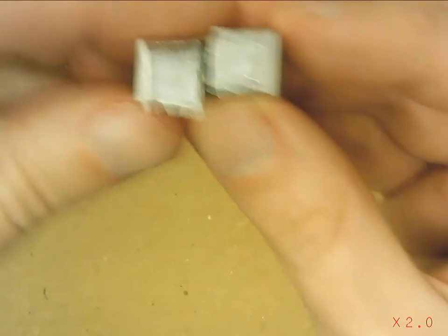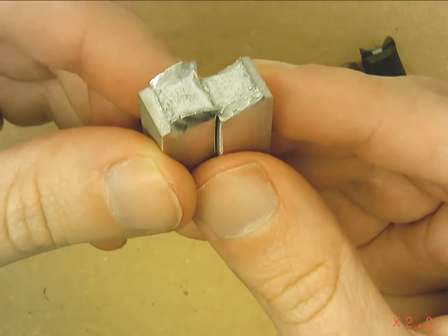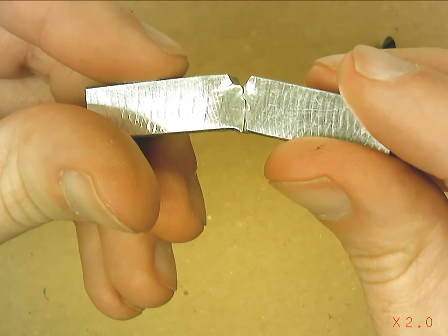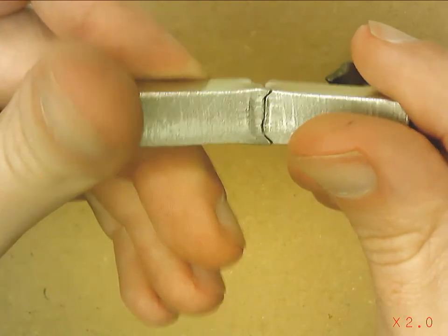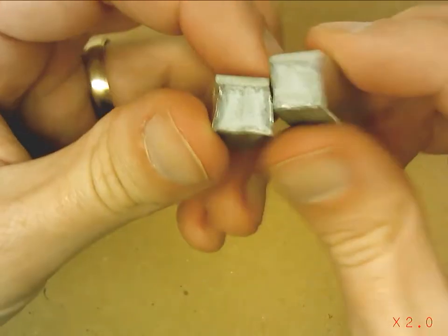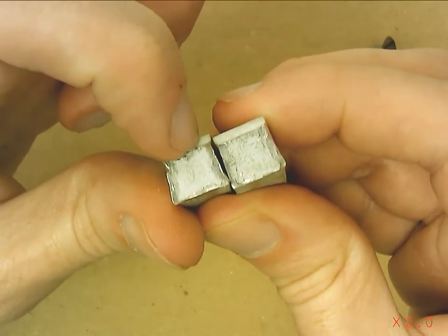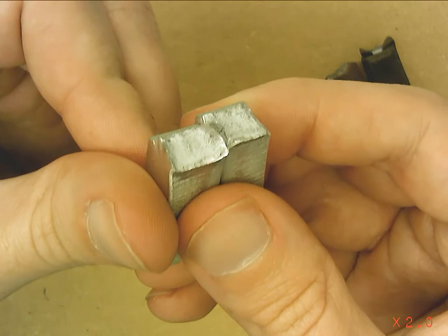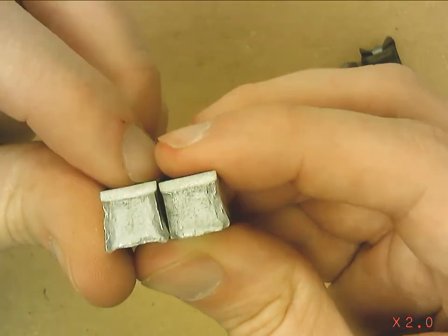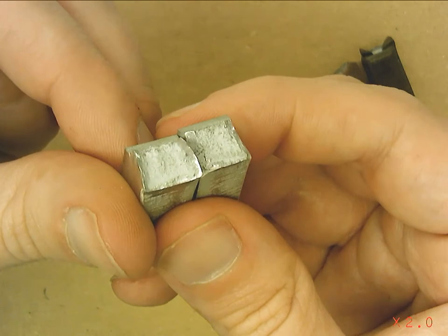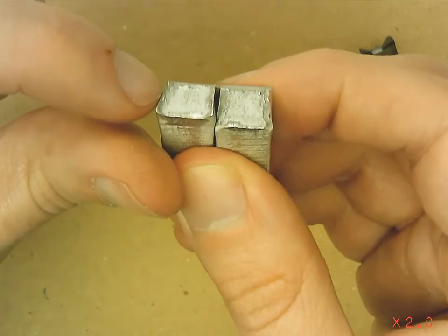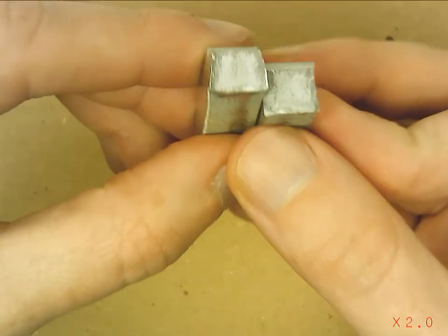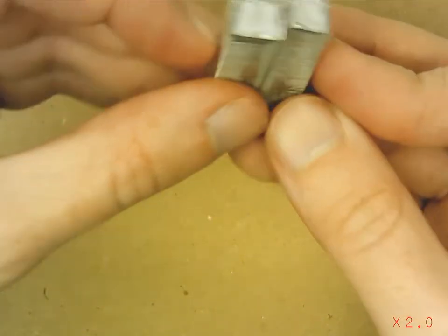We also have an aluminum sample. Let's see if that focuses. There we go. That's a little too reflective, but shows some deformation. Take the pieces apart. There's our notch up here that we're ignoring. And this is very ductile for the most part. The middle of it is kind of brittle, but the outside, there's an outside layer around it that's very ductile. I know that was 6061 aluminum, but I don't have the temperature. It looks like it's room temperature.